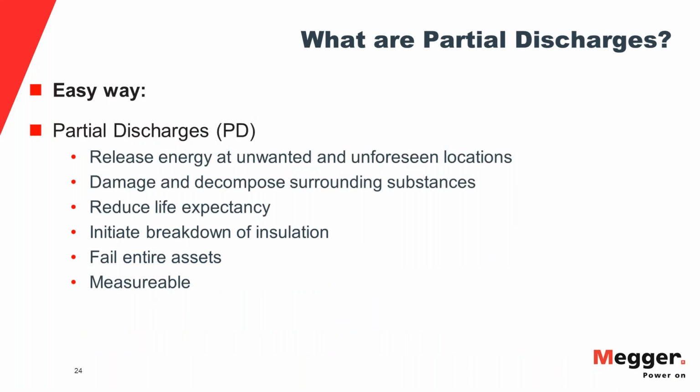And again, say it easy, use the soccer ball terminology. So you can say, what are partial discharges exactly in terms of practical operations? You know, you're in the field, what does it all mean? It's a release of energy at an unwanted and unforeseen location by means of design, okay? So somebody designed the cable and the termination, and the PD occurs in a spot where it should not be. That's pretty much what that means.